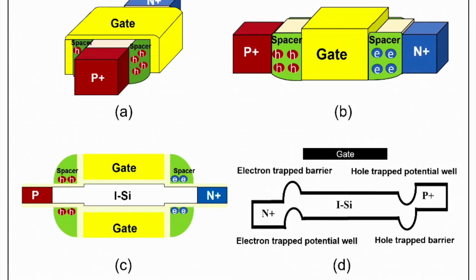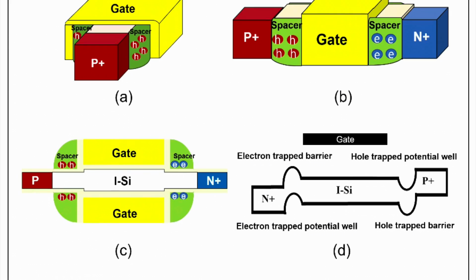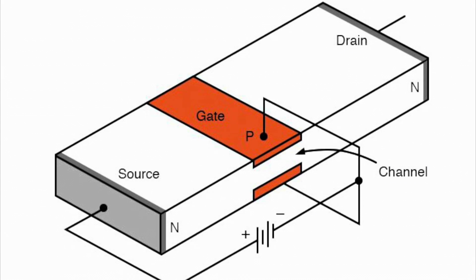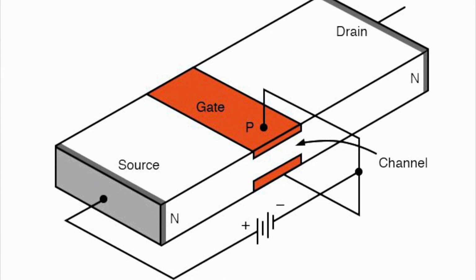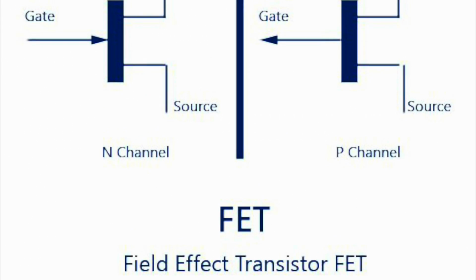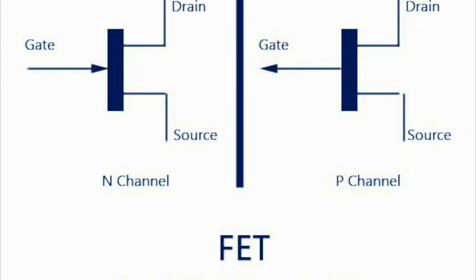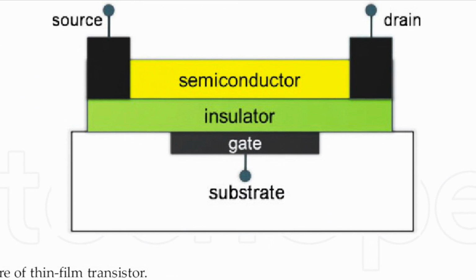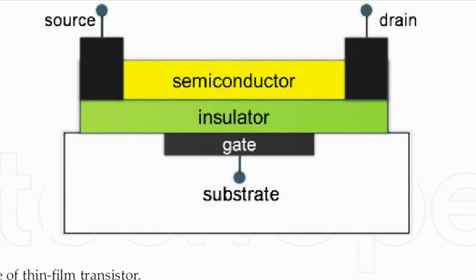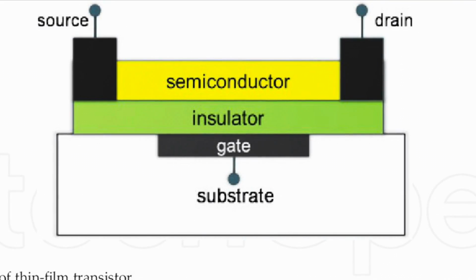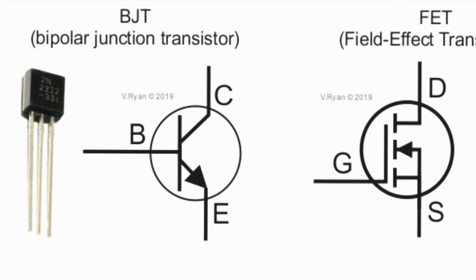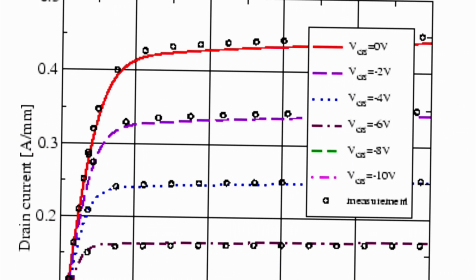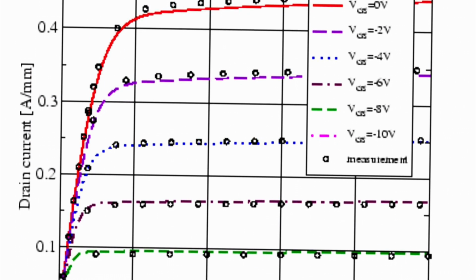This effect has also been used in many transistors and diodes, such as the previously mentioned MOSFET transistor, as well as the MESFET, or the metal semiconductor FET, which uses a metal semiconductor junction instead of the usual PN junction. The main difference between these two types of transistors is that the MOSFET usually needs the voltage to be greater than the threshold in order to pass the gate that would allow the current to pass, whereas the MESFET is usually on when a current is applied to it and will only turn off if a larger reverse voltage would be applied to it. The MESFET can be used for a variety of applications in many systems.